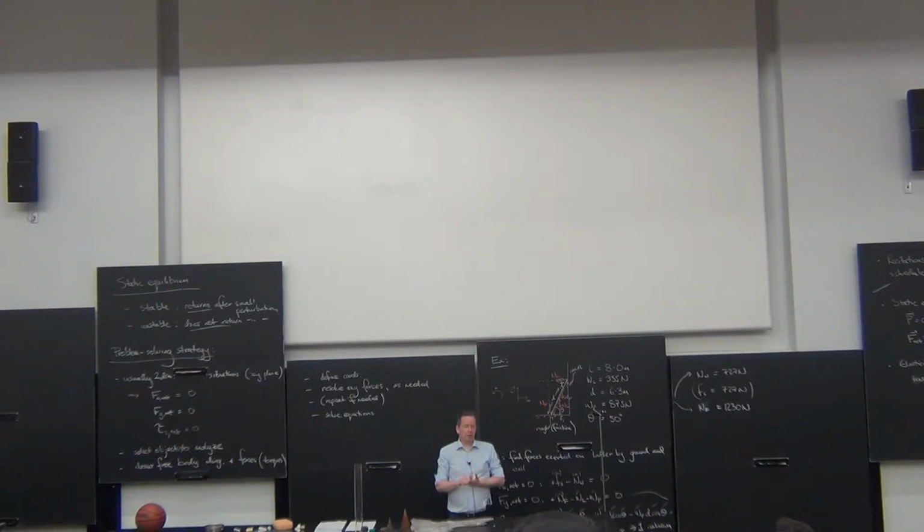Now, why am I saying that for our purposes they're the same? Formally speaking, when we're calculating the center of gravity, we're looking at the effects of the gravitational force acting on all mass elements of that object. If you have an object so large that its gravitational acceleration, or gravitational field, varies over the spatial extent of the object, then you will find that the center of gravity is in fact different from the center of mass.